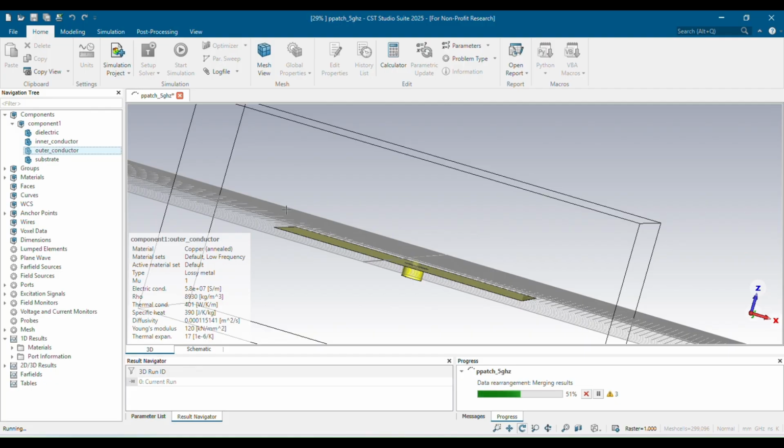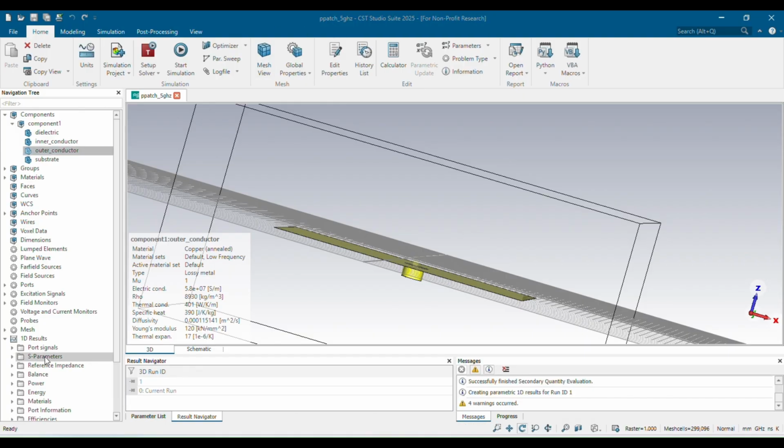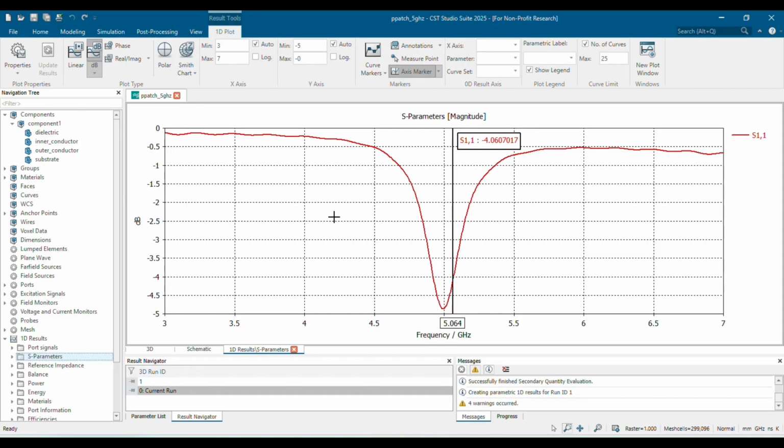millimeters as the radius. We can view the results, and then accordingly we can see whether we have to shift our coaxial feed cable more towards the center or away from the center, or more to the left of r by 4 or to the right of r by 4. We wait for it to simulate, and then based on the return loss values we tweak them. Remember that wherever we had r by 4, you have to change that.